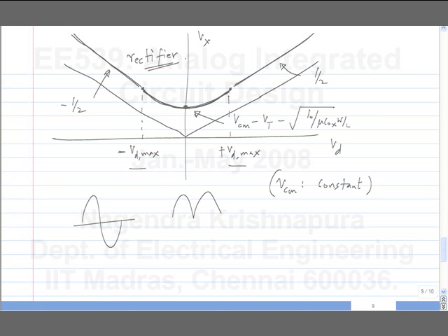A lot of times we deal with signals, in fact most of the time I would say, whose average value is 0. So if you just make linear operations on it, you will not get the strength of the signal. You will have to do something nonlinear to obtain the strength. So one of the things you can do is to rectify it. In general, even order nonlinearities give you a measure of the strength of the signal. It may not always be RMS value or anything like that, but it will give you an idea of what strength it is.